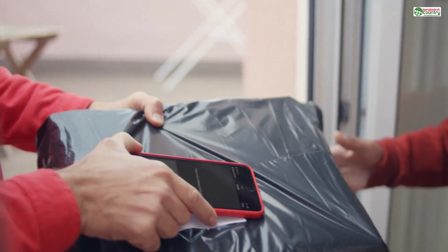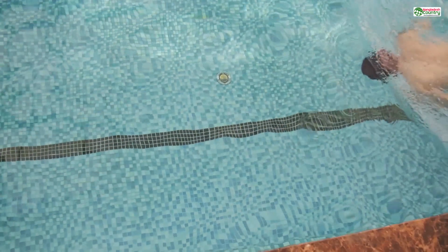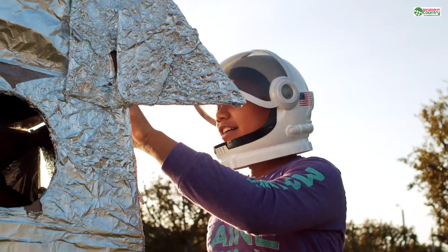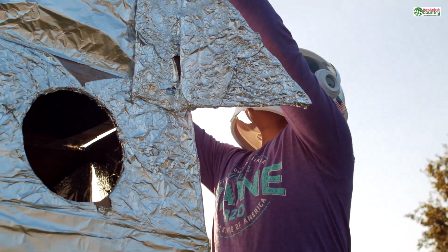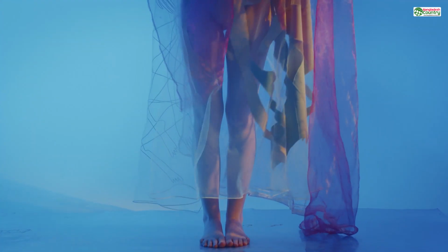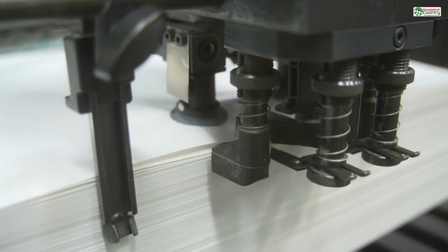Let's imagine you're printing a capital letter I. If you print it standing up, the two arms jut out at an angle. They'll likely be just fine right on that 45-degree edge. But now, imagine printing a capital letter T standing up. The horizontal top bar is a massive 90-degree overhang.